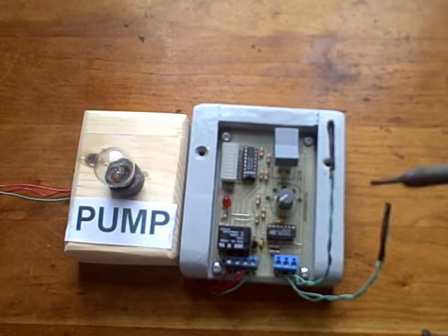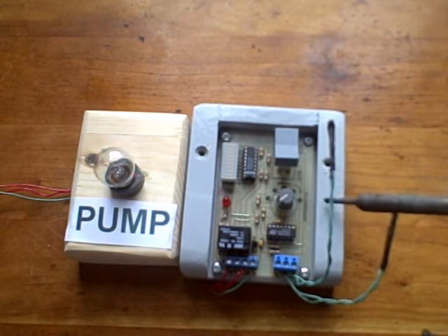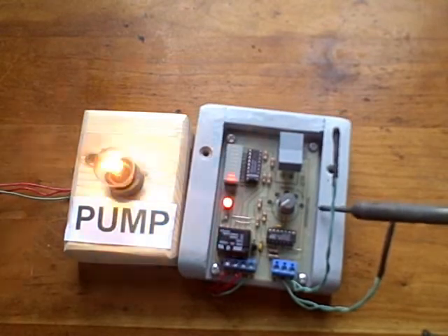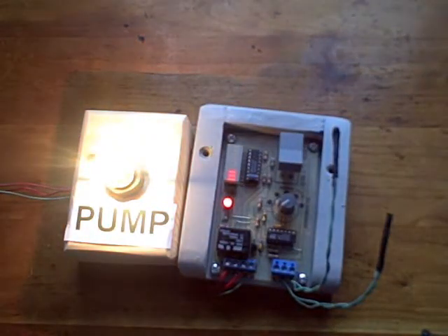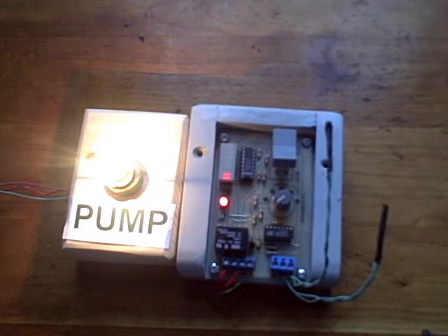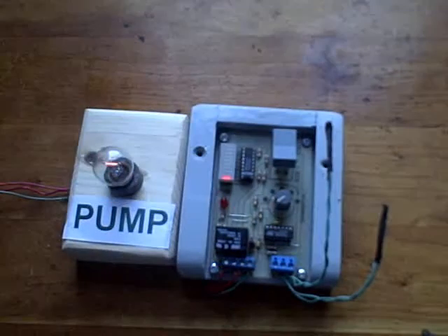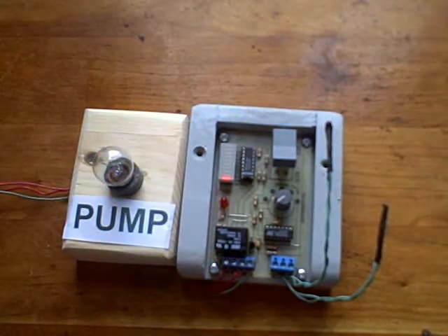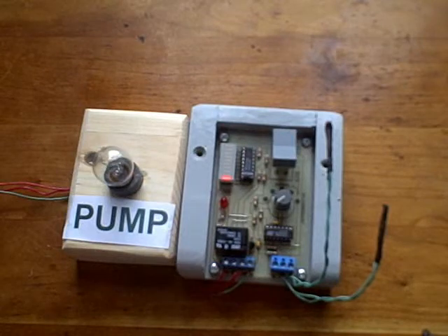So I want to heat up the collector temperature to turn the pump on. 70, 75, 80 degrees, the pump comes on. So that's a differential of about 10 degrees, and then the pump stays on for a while, and when it gets low enough, the pump should come off, and there it goes off. So the differential is around 5-10 degrees or so at the lowest setting.